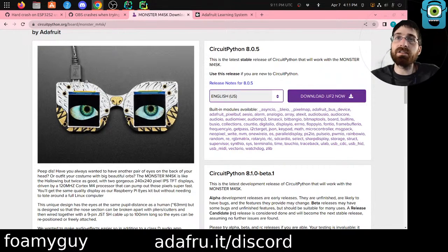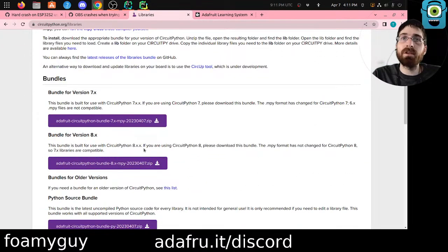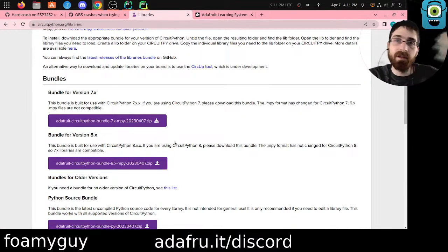Yeah, I obviously am going to be biased on that, but I certainly think having support for CircuitPython is a huge benefit because we do have loads and loads of libraries that are already written for lots of common hardware that you can take advantage of if you add CircuitPython support for your device. If it's one of the main chips that we already support, then adding support for your device is not that hard. You just define which pins are which and what flash storage you have and stuff like that. If it's a brand new main chip, a main family that does not have support yet, that's a much bigger task.